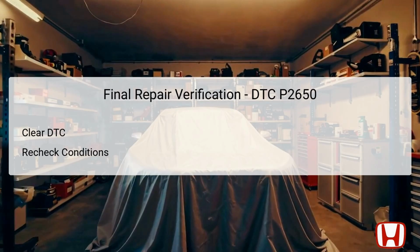Once all repairs are made, it is critical to clear the DTC from the PCM and conduct a recheck to ensure that the issue has been resolved. Use the HDS to clear fault codes and run the engine to monitor if the check engine light reappears.